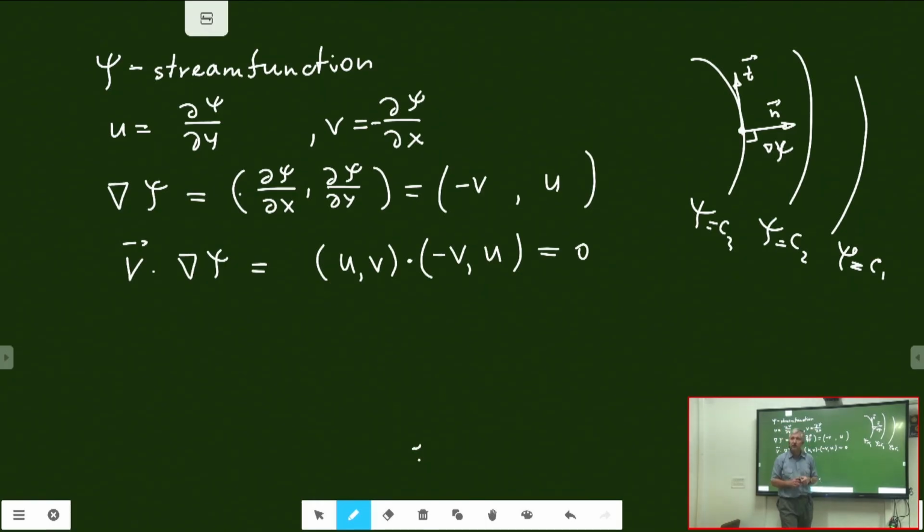Okay, so that's something to keep in mind. All right, so I'm sort of off track because that's a prerequisite material, but I don't mind. That is an important thing to remember physically: what the stream function is and what it represents and why. So the level lines, or contour lines, of a stream function correspond to streamlines, and streamlines are the lines along which the fluid flows. So that's what that is.